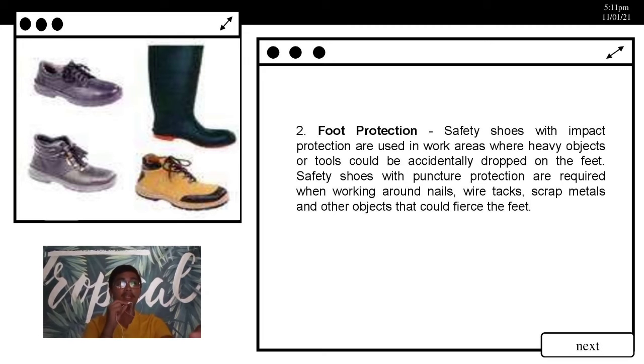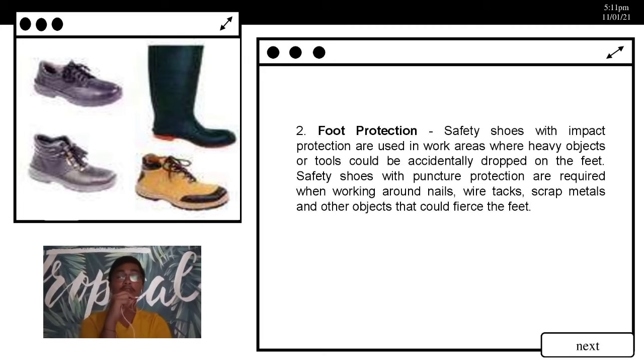So these classifications of the footwear actually have different markings with their own criteria and intended application. The first one is the green triangle, it has R on it. The green triangle indicates sole puncture protection with a grade 1 protective toe cap.